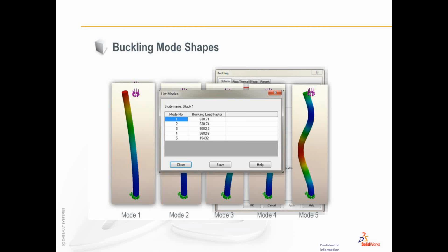In the case of a linear buckling study, although it allows you to look at multiple buckling load factors, it really doesn't make much sense to look past the first mode, because once the buckling load factor has reached the first mode, the structure is going to assume that failure mode, and it's going to buckle. It doesn't make sense to look at the next buckling factor because it's already failed, and after it's undergone buckling, you've now changed the structure dramatically, because buckling isn't